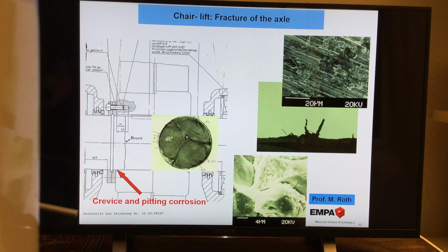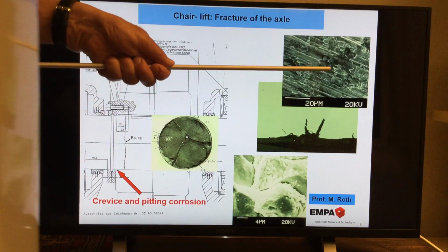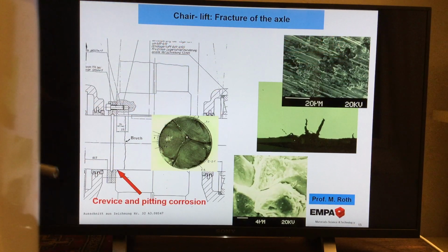And the original design, where there was no bundle and no screws, then obviously it could also breathe a little bit of gap, humidity, but it was not trapped. Not trapped. Look here, this is trapped by this design. So the moisture, the humidity is trapped here, and this makes here these corrosion pits, the start of it. So again, that was the explanation that 100